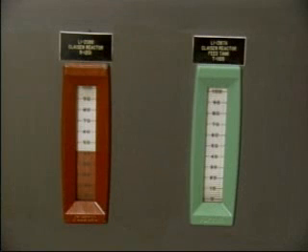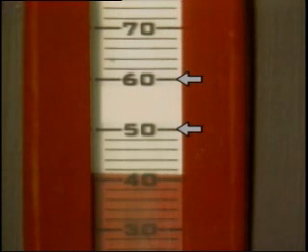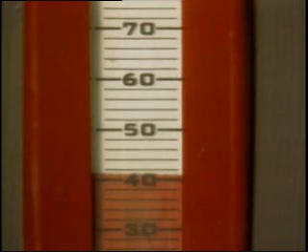Now, the way an instrument is read will also depend on the type of instrument you're working with. Indicators and gauges both have scales marked off in units of the variable being measured, and they're both read basically in the same manner. We'll use this indicator scale to see how these instruments are read. The major divisions on a scale are often divided into smaller units or subdivisions. The major divisions usually have numbers printed next to them, but subdivisions may not.